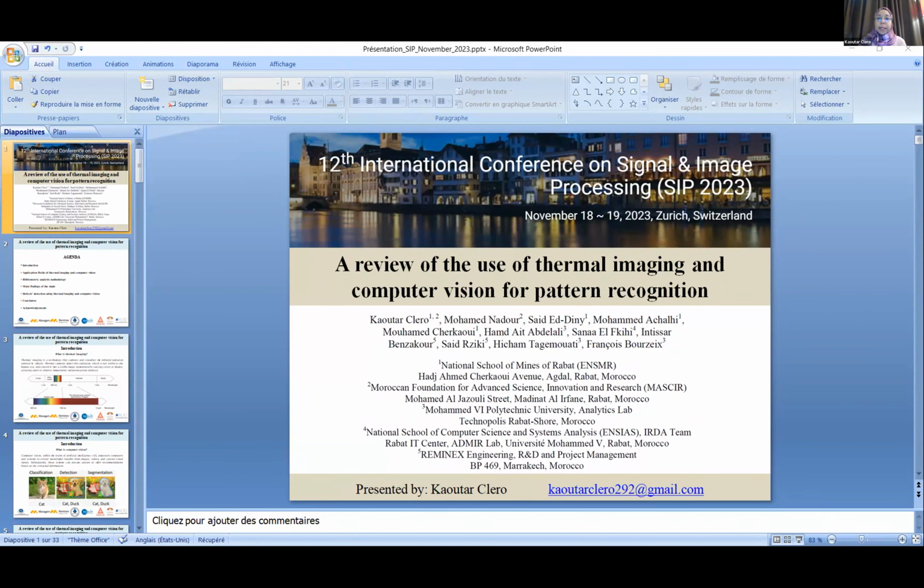So the other bands cannot be seen by humans. So thermal cameras detect the radiation in the infrared part of the spectrum and convert it into a visible image represented by varying colors or shades, which allow users to observe temperature variations across surfaces. In a thermal image, each pixel corresponds to the temperature at its exact location.